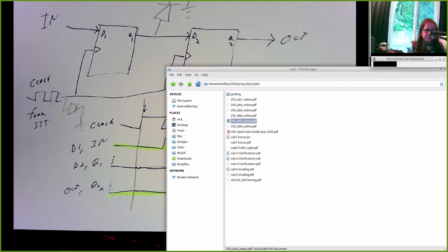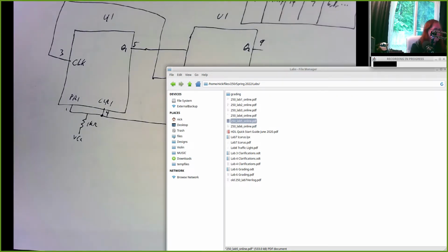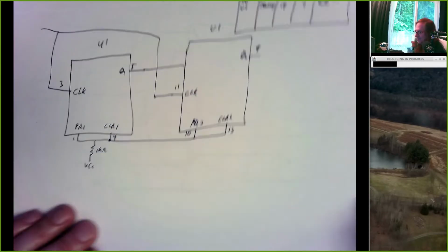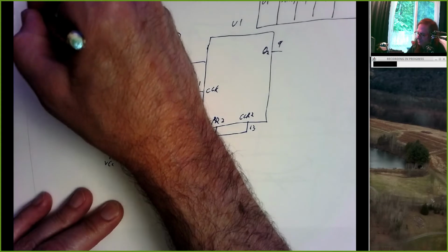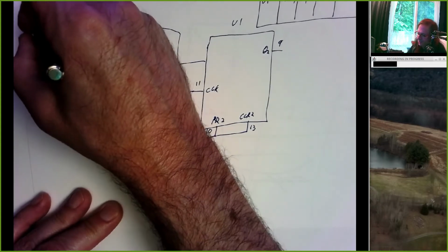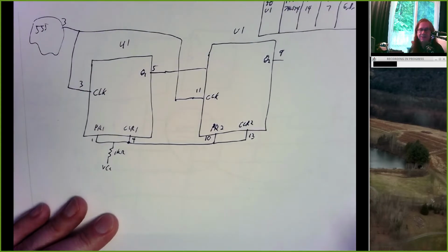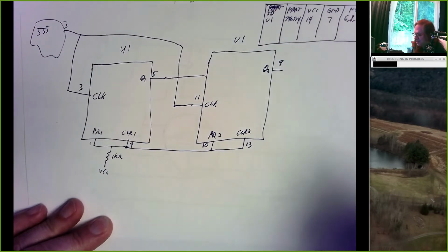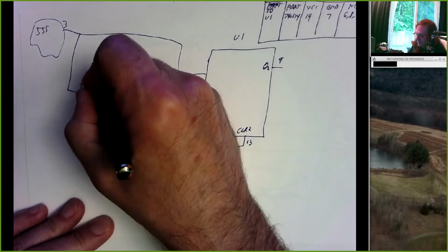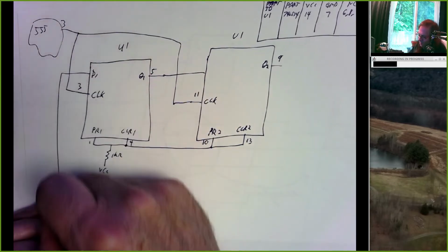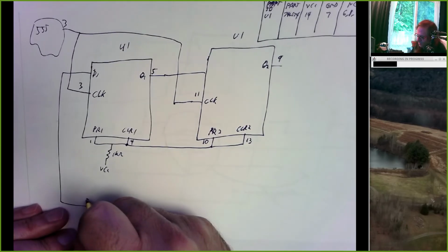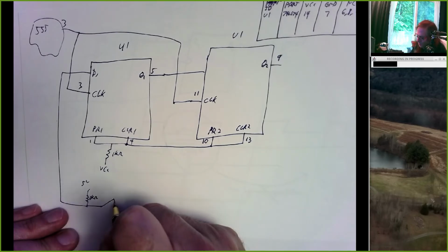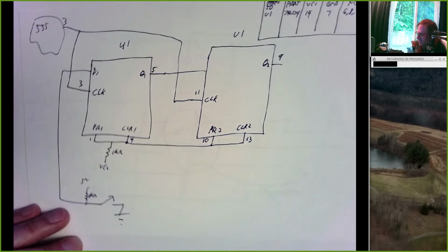So wire it up with part numbers and pin numbers and component ID block, and all of that good stuff. And we're probably going to have a block over here with a 555 and pin 3 coming out, so that's got to be included, right? Because it's part of your circuit. And then this D1 input is going to go through a switch that we can connect to ground.